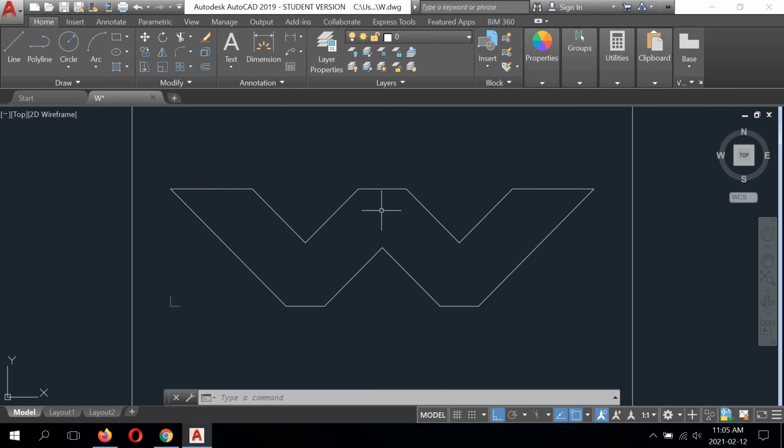Pretty slick to use your mirror command. Now, mirror can't be used all the time. Sometimes it's counterproductive in certain cases, but it can be a real time saver if you have to work on some features on a drawing that require a lot of symmetry. So basically with this drawing, we basically just cut our workload in half with a couple of clicks of a button. So that is the power of AutoCAD. As we keep going, we're going to be revealing more power from the program and how it really helps us to draft and design objects.